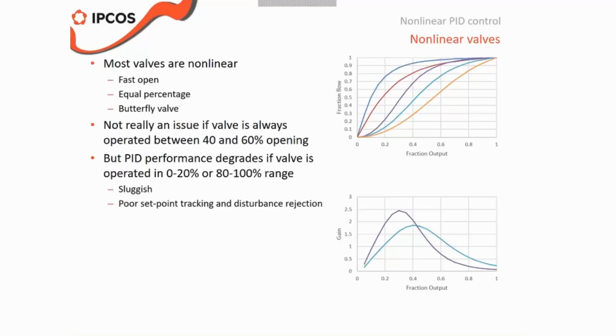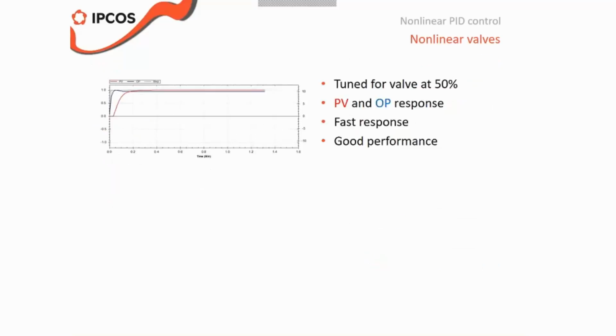That raises the question, if I have a PID controller, which is a linear controller with just one set of tuning, how do I tune this? I could tune it for 75% load, or let's say at 100% load. So if you don't do anything special in the DCS, you just optimize the tuning of the PID controller. For which valve, which operational point should I tune it then?